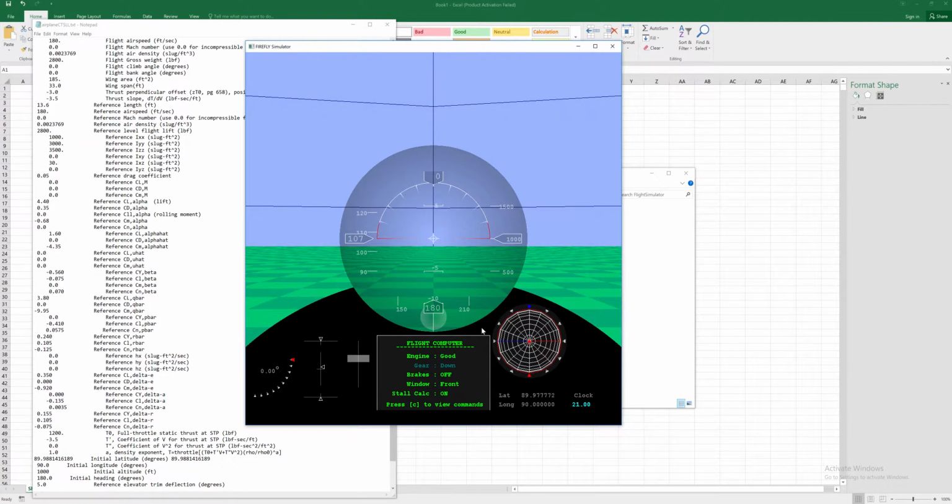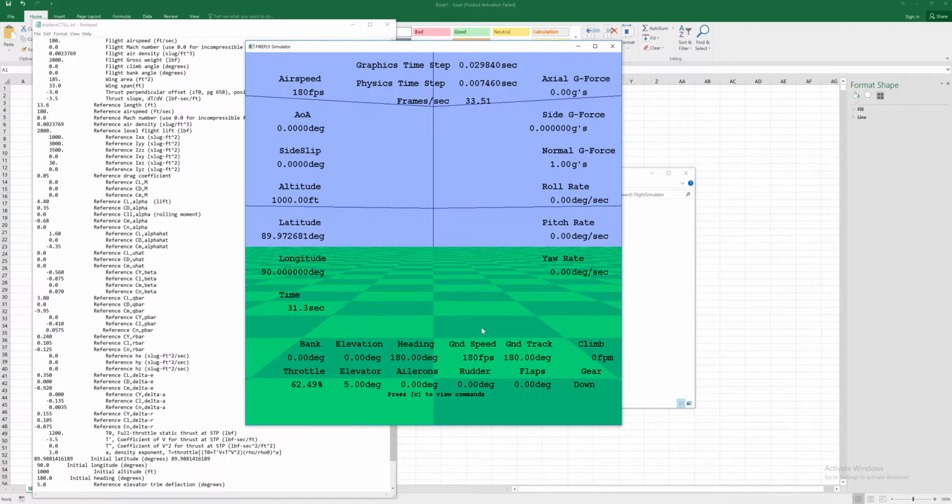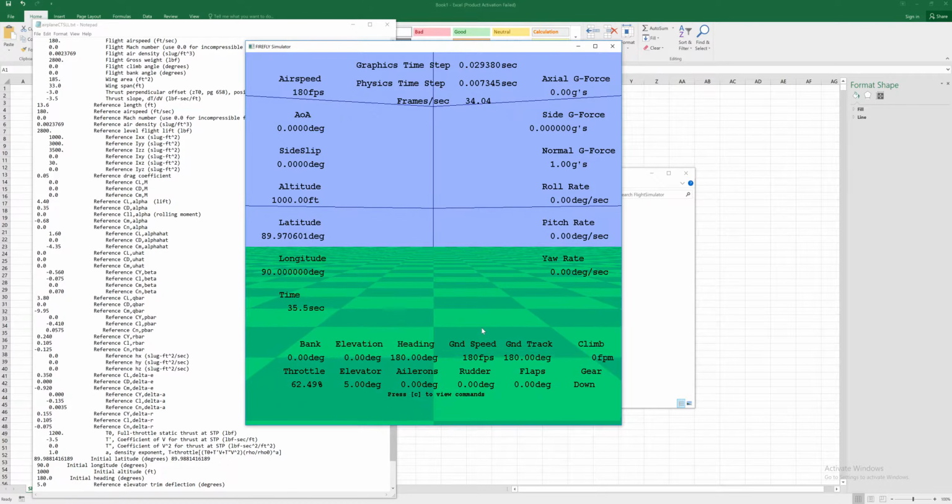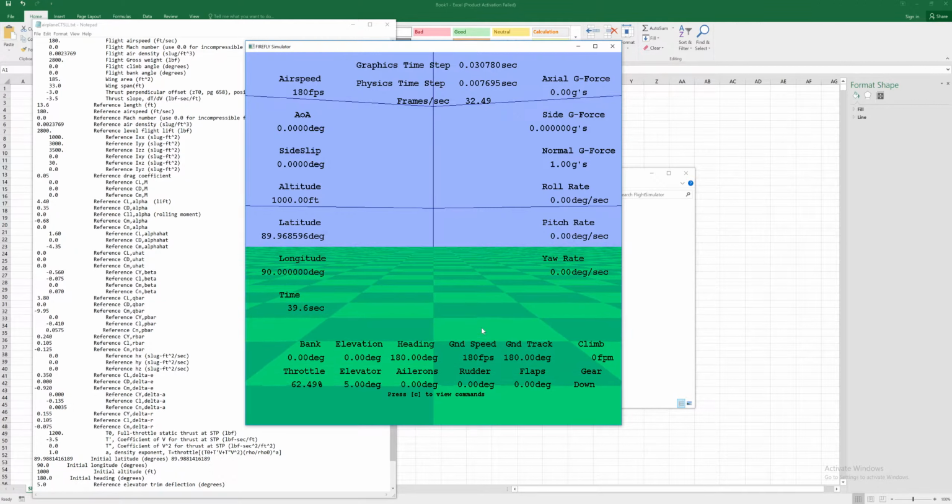Now, in flight testing, this is a very common maneuver where they basically hit the stick with their hand. So I'm just going to put the step input in with the elevator. I'm going to pull back sharply and let go sharply, more of like a whack. I'm just going to hit the stick, and then it's going to excite our longitudinal modes, and I'm going to try not to excite any lateral modes here. So let's see how this goes.